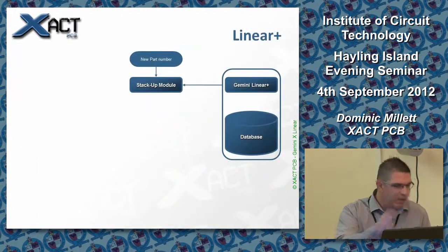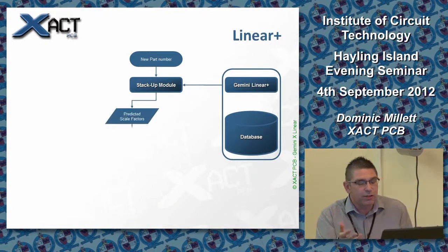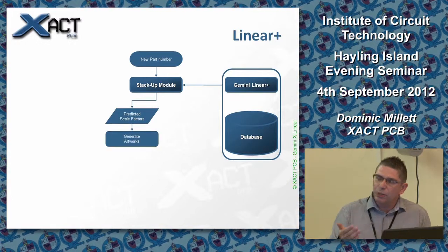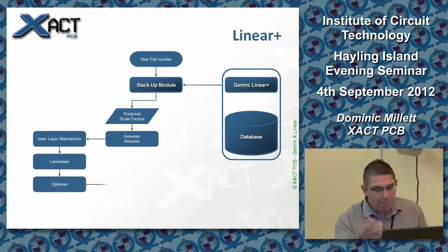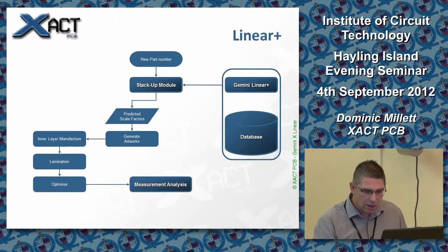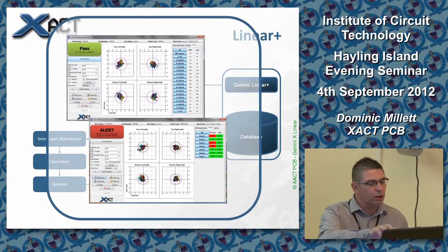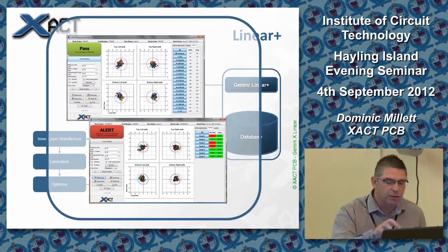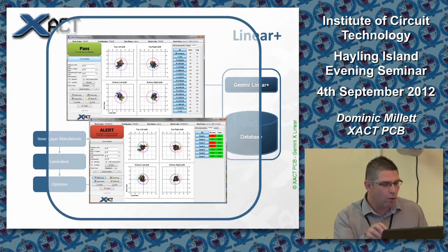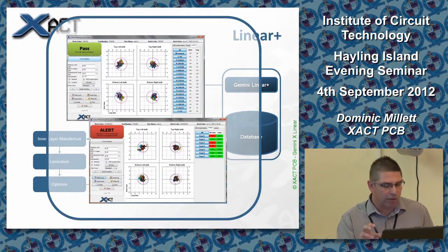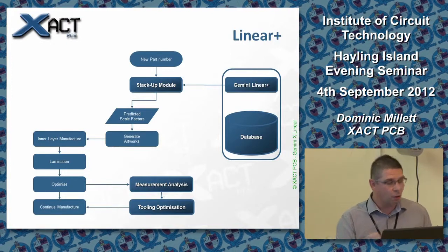Let me give you a very brief outline of the system, the idea of what it is. You have the stack-up. The system gives you predicted scale factors. These are your artwork scale factors you apply in production. And then after the bond cycle, you measure the panels. That measurement data, those coordinate measurements, are then matched with the stack-up information fed into a database. This is a screenshot of the measurements of the particular panels you just measured on your X-ray or vision system. These are the four corners of the panel showing worst case registration errors. The system also generates an optimized drill program to give you a best fit for all of the inner layer parts.